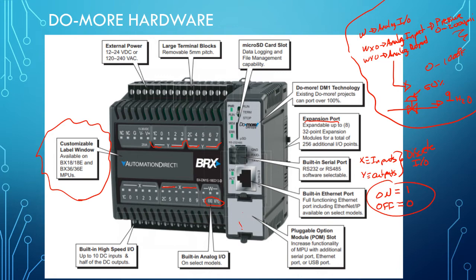For our class, we will use this port right here, convert it to USB, and we will program using that port. Then we will switch every now and then to another port called RS-232, to communicate with and power our HMI.